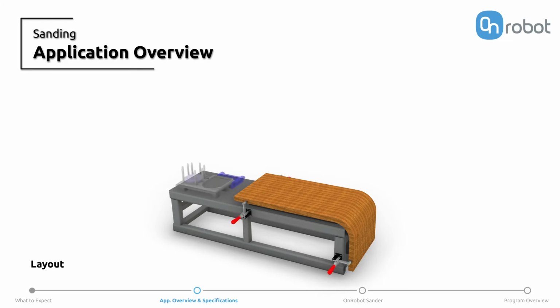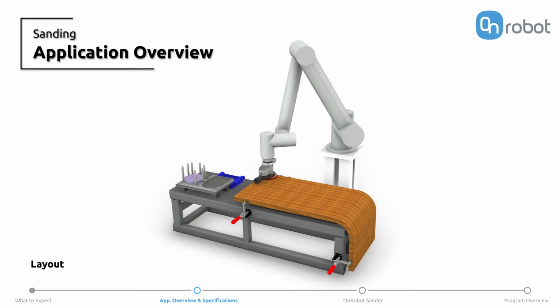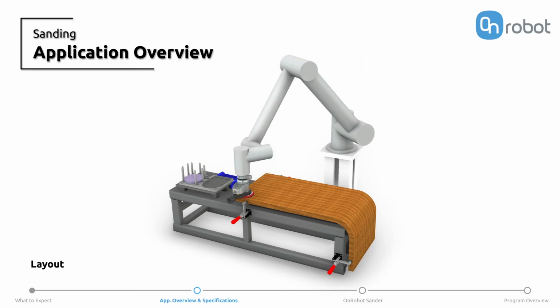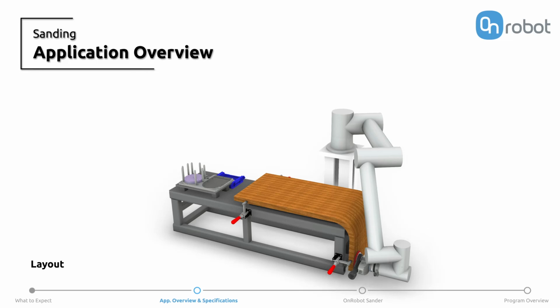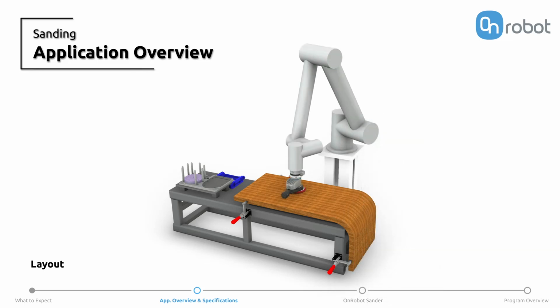secured. The robot should also be mounted at a position where it will be capable of reaching the complete surface without overstretching, as this could create a high torque on the arm and introduce vibrations that will negatively impact the surface finish and the robot arm.